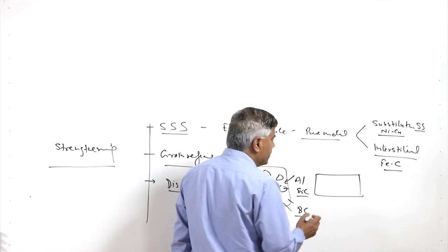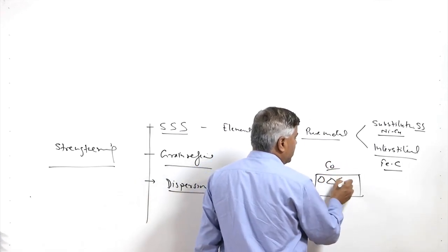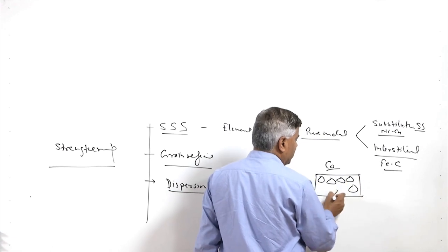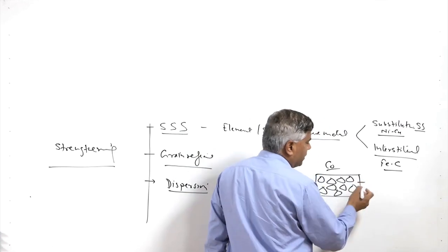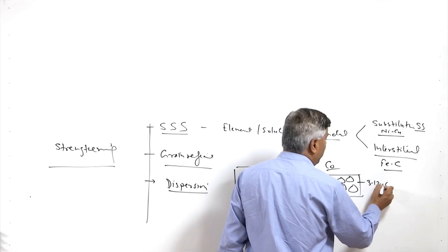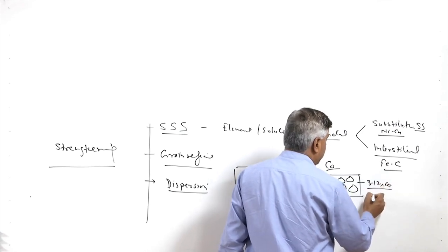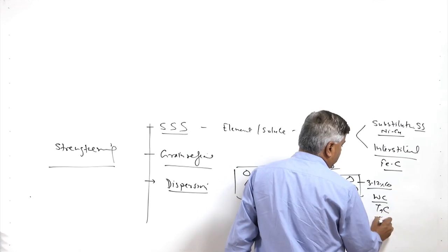and carbide tools are one of the examples wherein, in a cobalt matrix, carbide particles of tungsten, titanium, or tantalum are fitted. The proportion in carbide tools may be 3 to 12% cobalt and the remainder tungsten carbide, tantalum carbide, or titanium carbide.